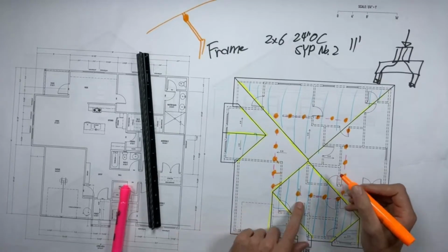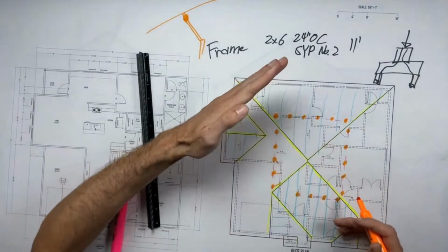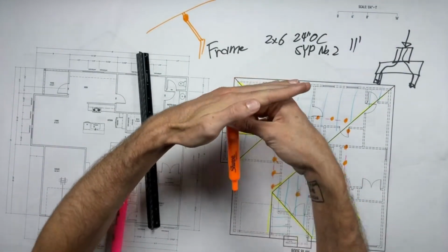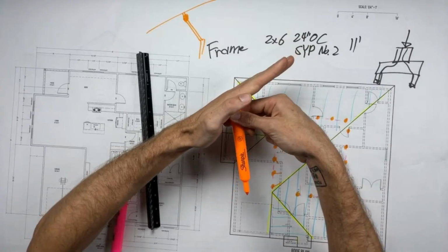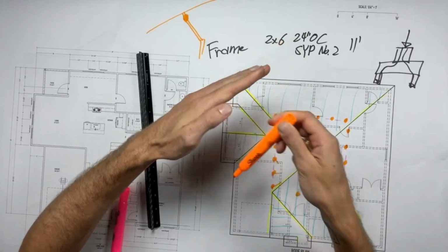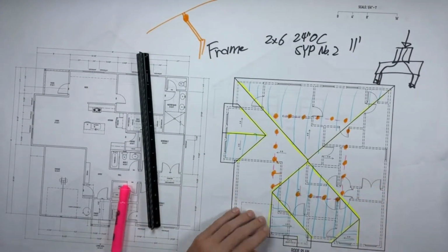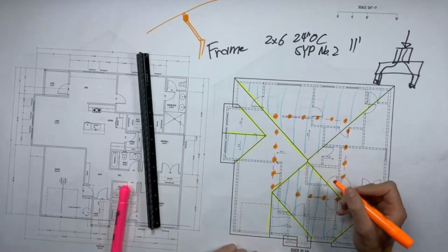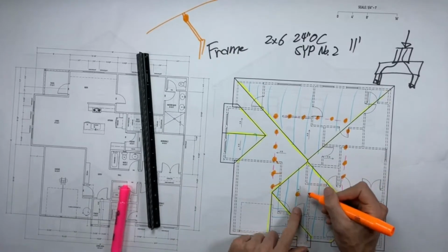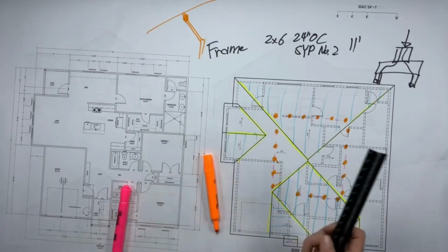Over here, now keep in mind, the rafters are slanting. If we were to section this, they're slanting up like this. We want the brace to be sort of perpendicular. It can either go straight down or go perpendicular to the plane of the roof. You don't want to try bracing back the other direction. It's not ideal, and it's a weird connection to make. So you want to try to brace against the slope. This one has a wall, has a wall, has a wall. This one doesn't, but maybe we can reach this wall over here. Let's find out if we can. How do we know if we can?